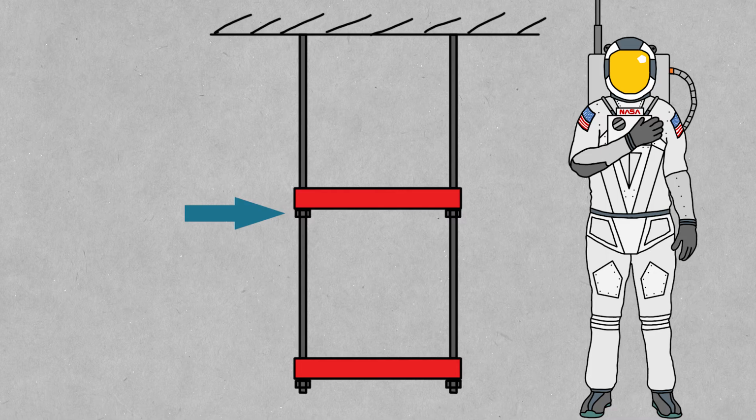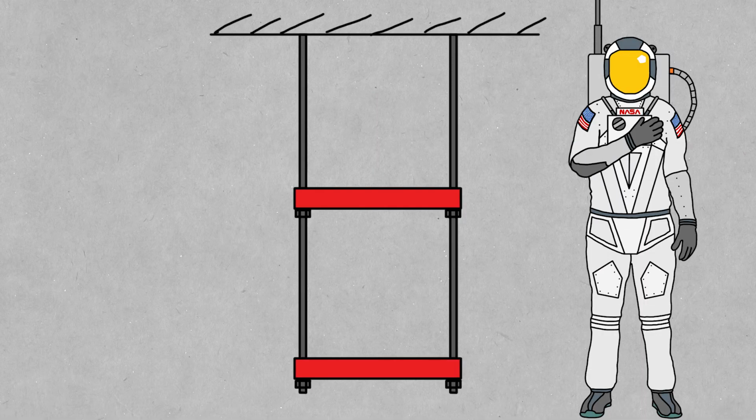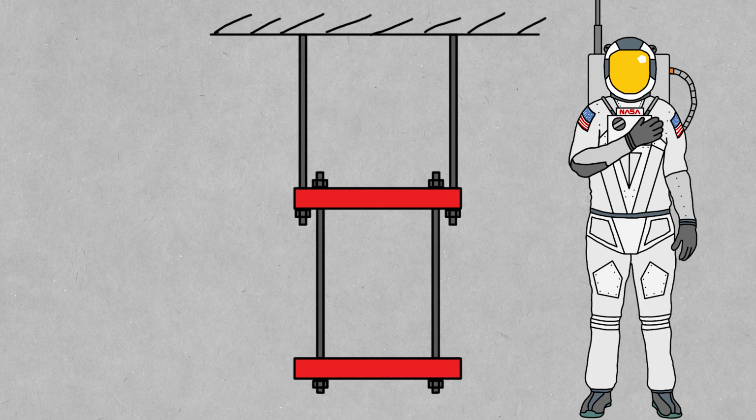The construction company understandably did not want to thread nuts up 2 stories worth of rod, and they were also worried that they could easily damage the threads on the rods when they were installing these walkways. Because of these concerns, an alternative plan was proposed, which split the rods into 2 so that only the ends needed to be threaded. This plan was approved by engineers, who were ultimately found at fault for the disaster.